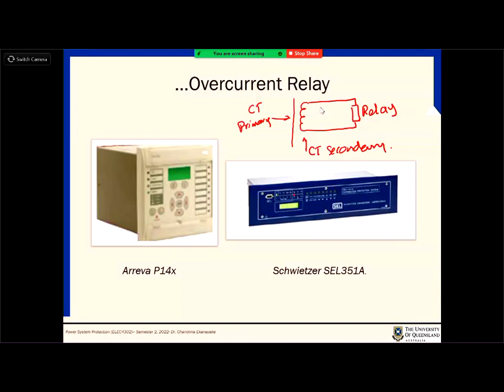That kills the whole insulation system. Okay, so if you look at it even in the laboratory or field environment, you never keep the current transformer's terminals open. You can keep them short circuit, no problem at all. You can keep them short circuit, but you can't leave them open, right?